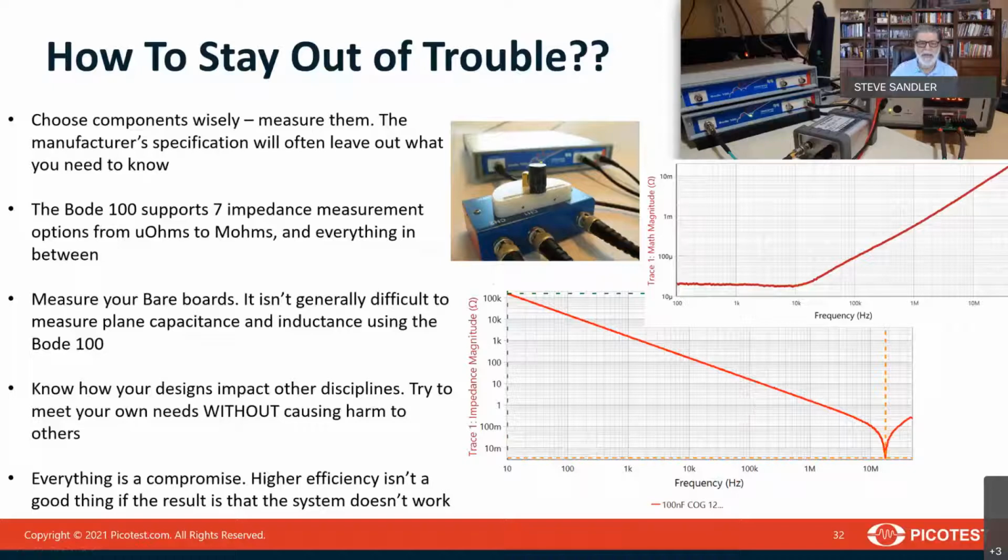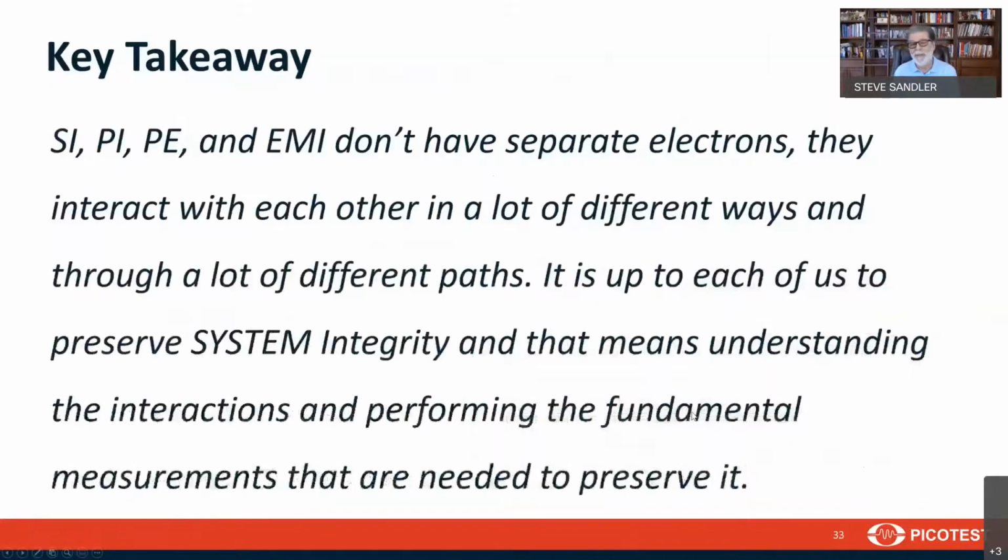But we will not use a capacitor that we have not measured. We won't use a component that we have not measured. So that's probably the best thing you can do to stay out of trouble: measure the impedance of your components, measure the impedance of your circuits.